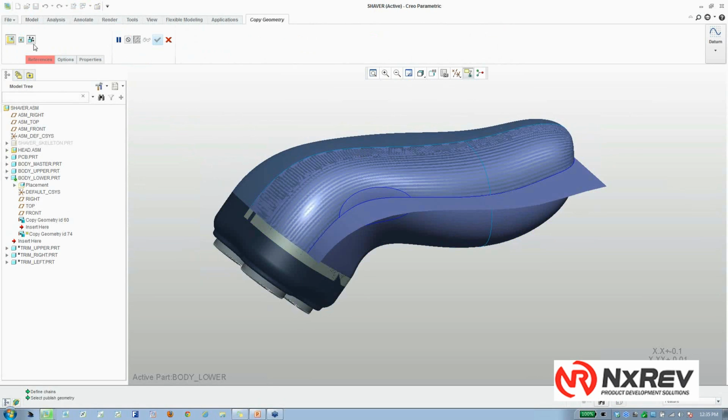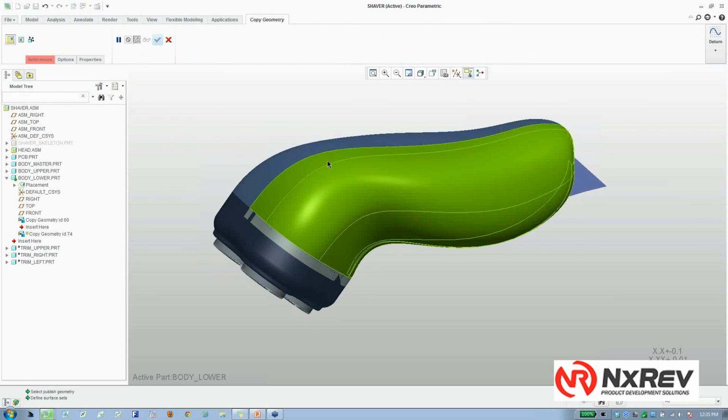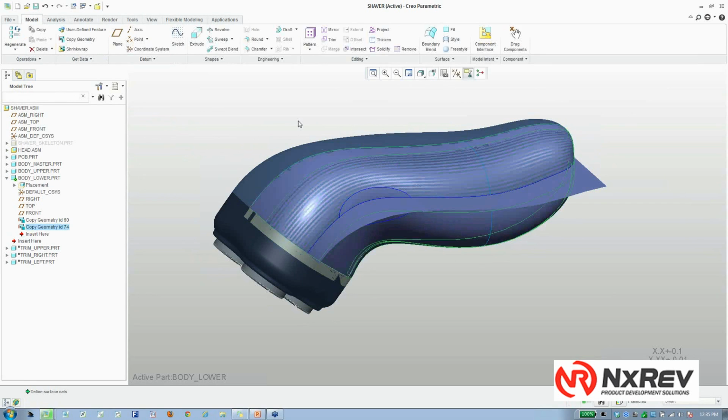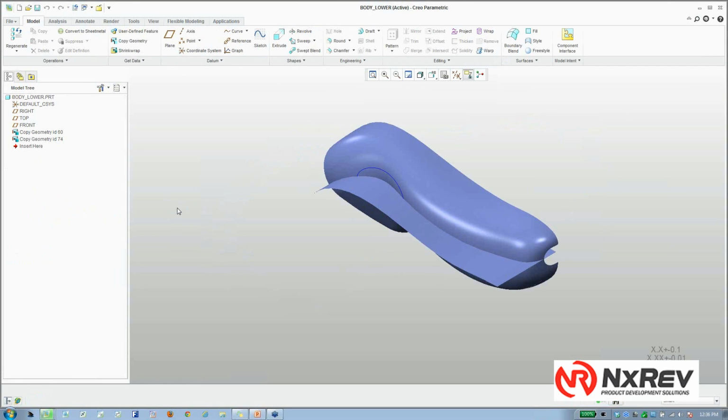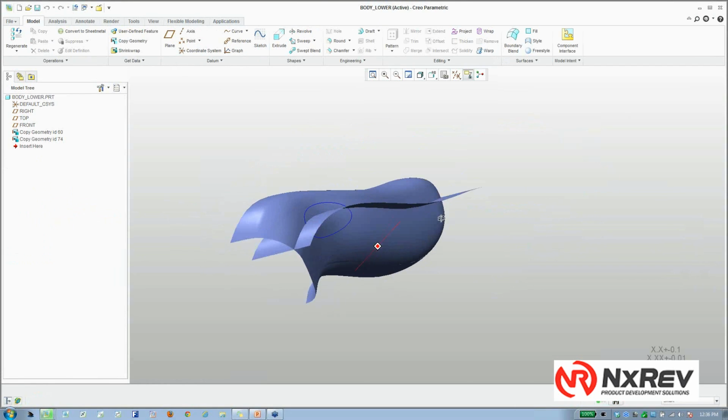And then we'll do a second copy geom to add the surface from the master model there. Okay, and if you see me pre-highlighting like that, what I'm doing is I'm query selecting and right mouse tapping until I get to the surface that I want. All right, so let's just isolate this part by itself by opening it and further refining this part.